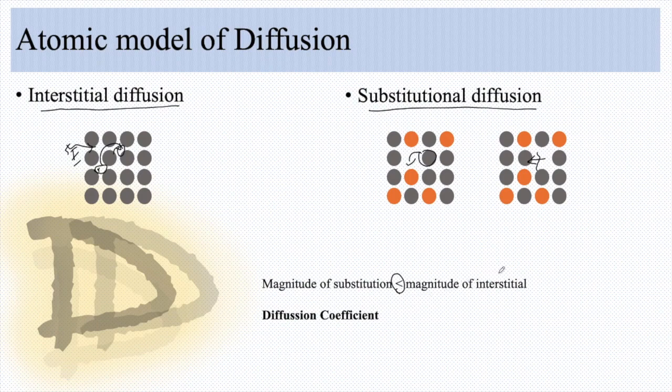As given by the diffusion coefficient, the diffusion is larger in grain boundaries than for the lattice, because of the pre-exponential constant of diffusion. However, the cross-sectional area across which the mass transfer occurs is less for grain boundaries. At high temperature, lattice diffusion becomes important.